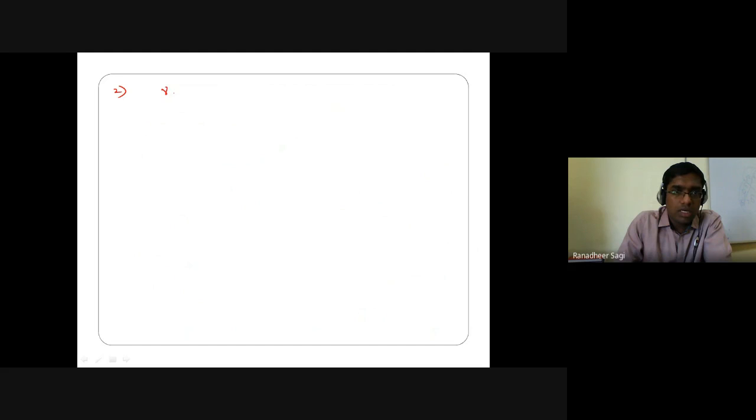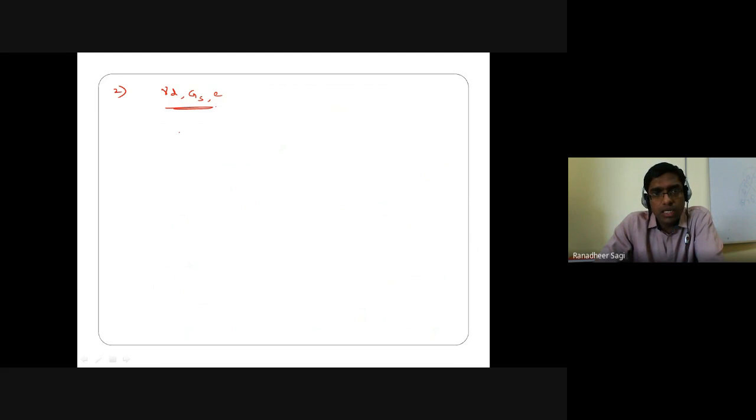In the same way, let's see another relationship, how we can derive a relation between the parameters dry unit weight of the soil, specific gravity of soil solids, and the void ratio of the soil. So let me understand that dry unit weight is nothing but the dry weight of the soil, which we write as weight of soil solids divided by the total volume of the soil. Earlier we have seen this expression for dry unit weight.